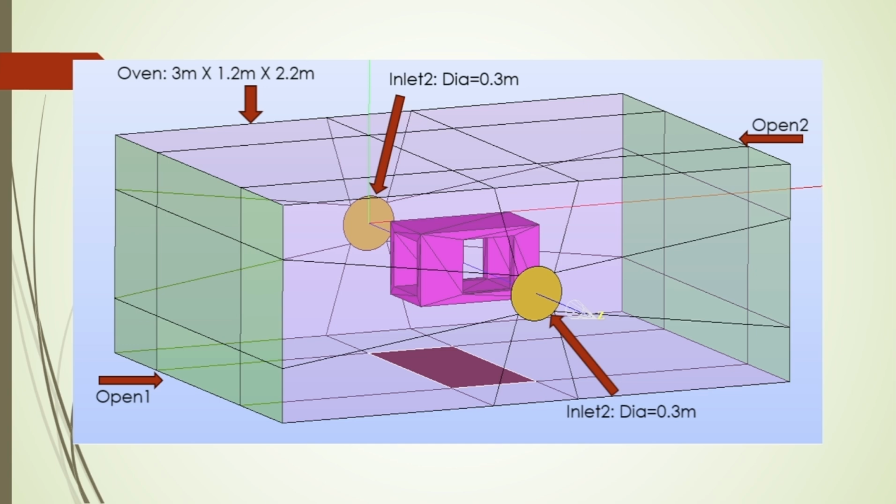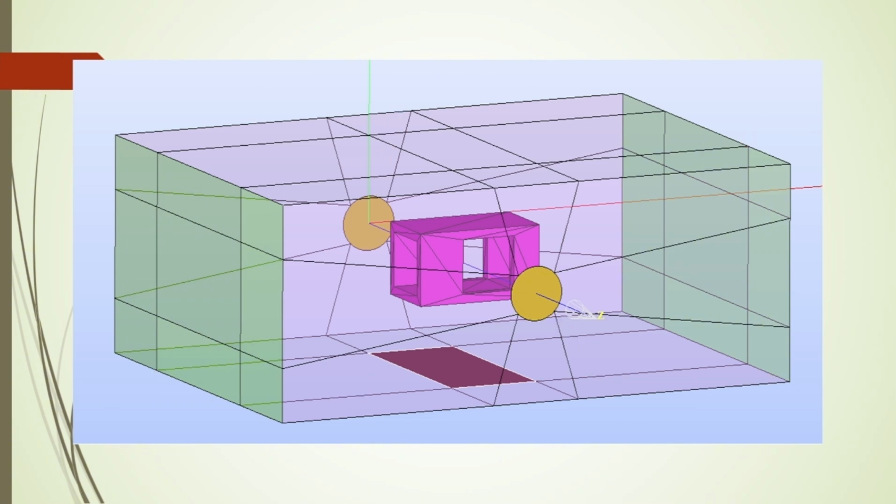However, in the current simulation, I specified a pressure outflow boundary condition. A rectangular outlet is provided at the bottom and a pressure outlet boundary condition is specified. For the present study, I created a simple manifold geometry as shown. I could have used a car geometry, but it needs to be repaired to make it a perfect manifold geometry. Hence, I created a simple object.